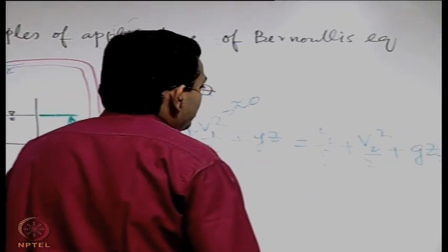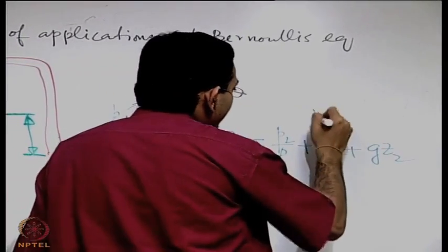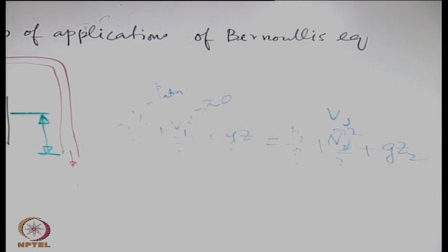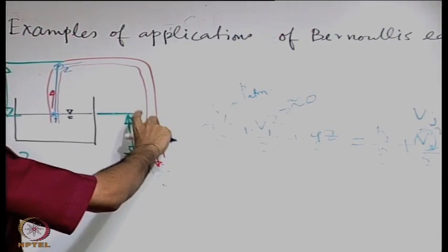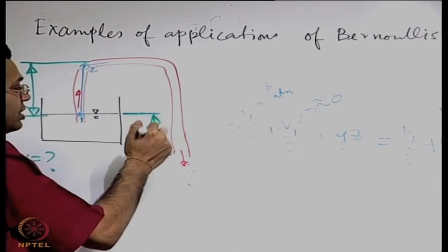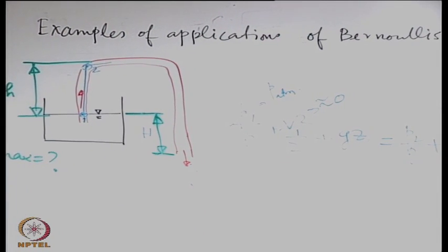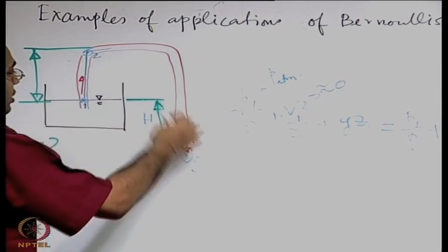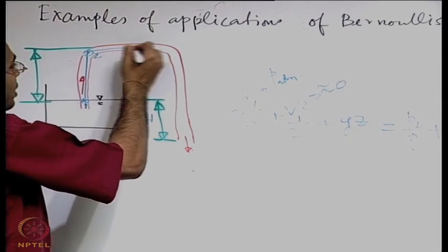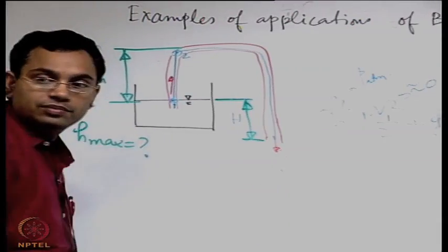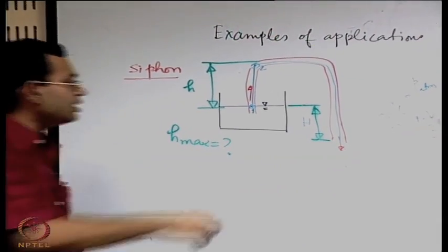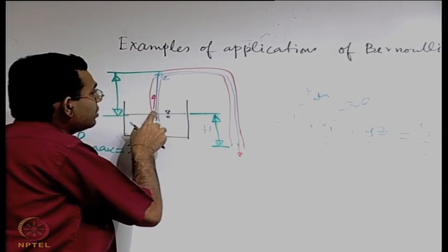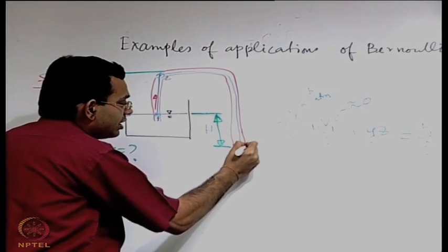Then V2 is equal to Vj, the velocity at which the jet is coming out if the cross section is the same, and you can find that Vj is approximately root 2 g into this capital H, by writing the Bernoulli's equation between 2 points on the same streamline, if you continue with that streamline, it goes like that and comes out. The net elevation difference will remain this one if you write the Bernoulli's equation along a streamline between points 1 and a point j which is located here.